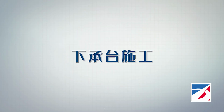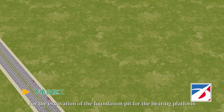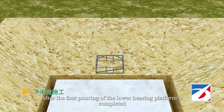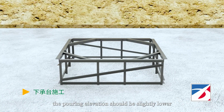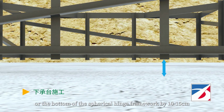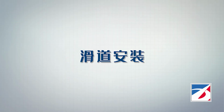Construction of lower bearing platform. For the excavation of the foundation pit for the bearing platform, the concrete for the bearing platform is poured in 2 stages. After the first pouring of the lower bearing platform is completed, the pouring elevation should be slightly lower than the design elevation of the sliding tracks bracket or the bottom of the spherical hinge framework by 10 to 15 centimeters. Sliding tracks installation.